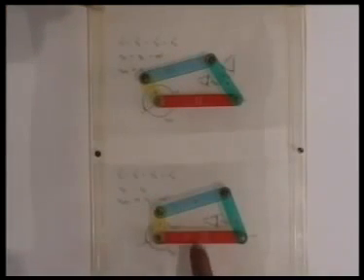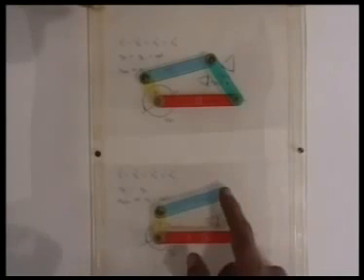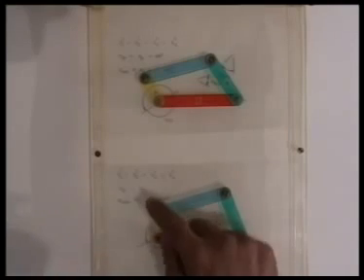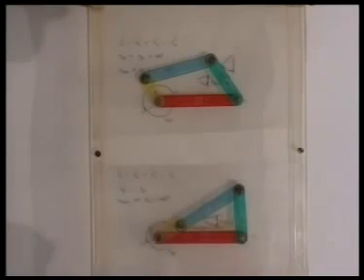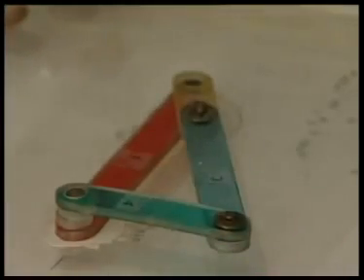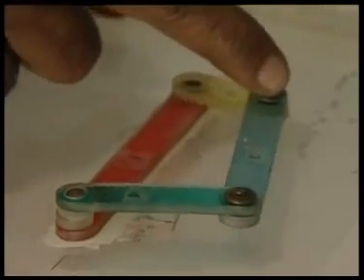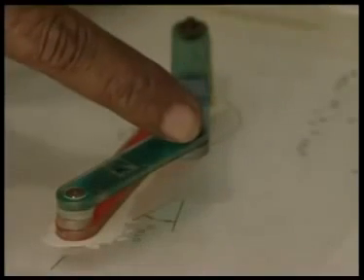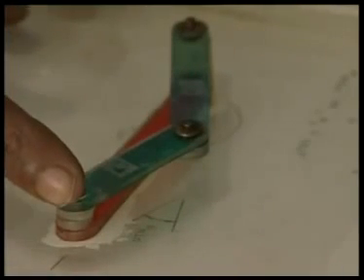Now, let us look at the model of this crank rocker linkage where L1 squared plus L2 squared is not the same as L3 squared plus L4 squared. As a result, the extreme position of the follower that it takes is due to unequal rotation of the crank. One extreme position is here when the crank and the coupler have fallen in one line. Now, from here it rotates through this angle, again the crank and the coupler fall in one line, giving rise to the other extreme position of the follower.